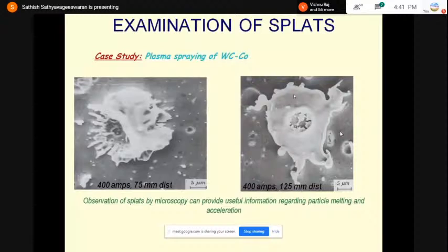Moreover, in this image you can see that the coating thickness is uniform throughout the entire material. If you measure the thickness, I can say that it will be approximately 300 micron. At the bottom you have a scale, which is mentioned as 100 micron, and if you place the scale over the coating, it will be almost 3 times. So it will be around 300 micron thickness.